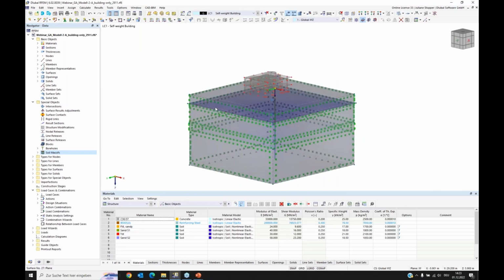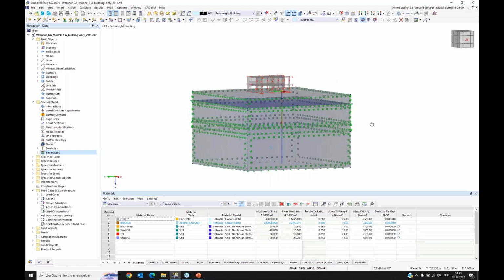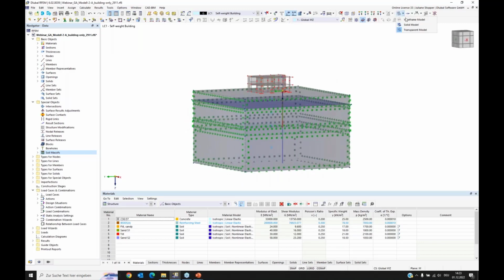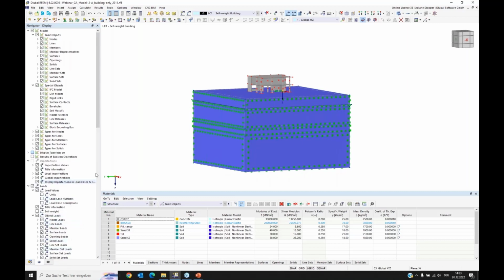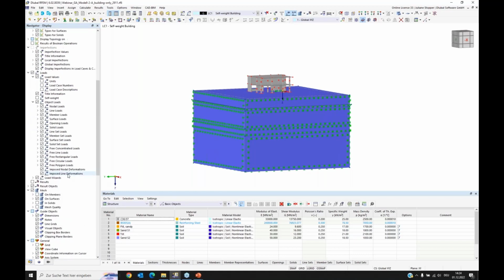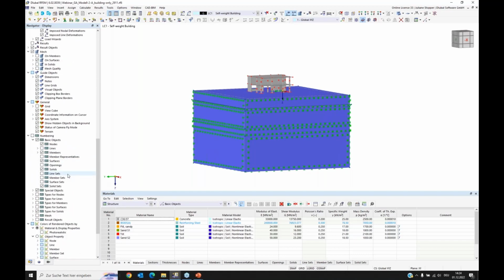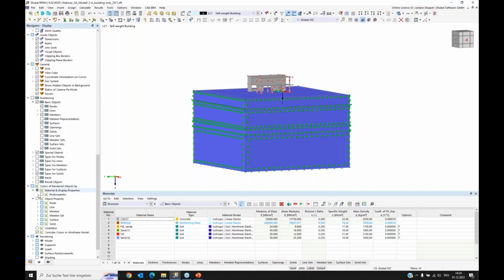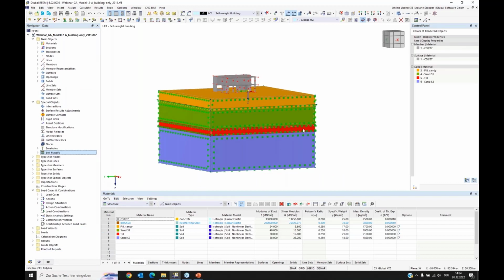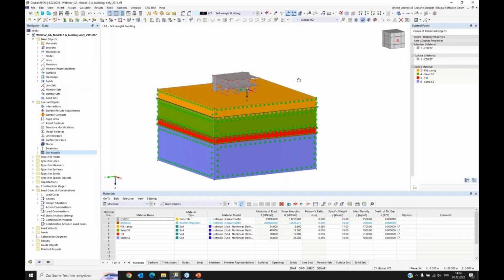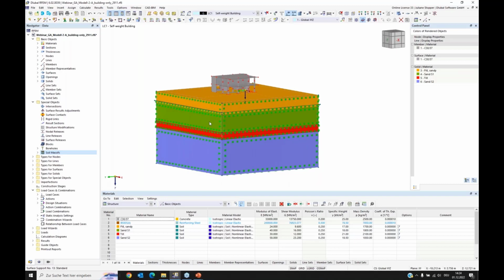And here we can see our soil massif. And we can see quite well the groundwater level surface. And I will set the solid model, and I will go here to the navigator display where you can set display settings. And I want my model to be displayed in the colors dependent of the property, the material. Okay, now I can see the soil layers quite well.